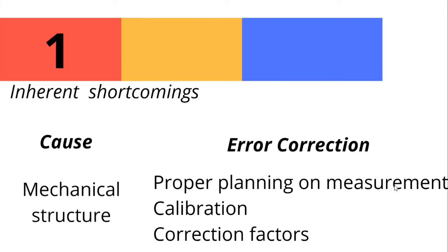Whereas if you don't have that, we'll have to properly plan for the wire that we have in our hands, right? So how can we do that? First will be removing hair, then using proper gel, right? So that is the error correction strategy. That is the first point, which is proper planning of the measurement. And the second one is calibration. Since we are not using a predefined sensor or electrode, we are using something else. That something else should be calibrated properly with the golden standards, right?